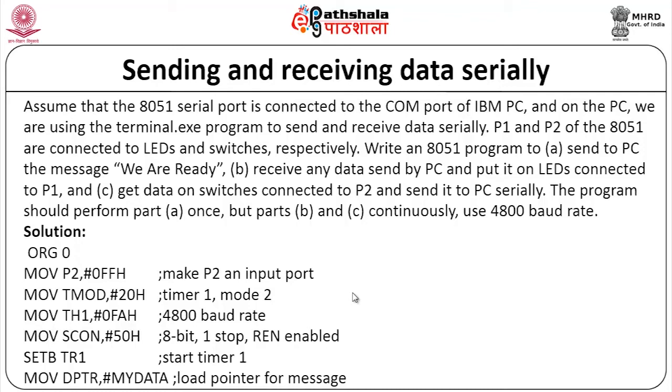The task we need to do is to write a code in 8051 assembly to send the PC the message "we are ready". So some message has to be sent to your PC serially, and we receive any data sent by the PC and put it into the LEDs connected to port 1, and get the data on the switches connected to P2 and send it to the PC serially.